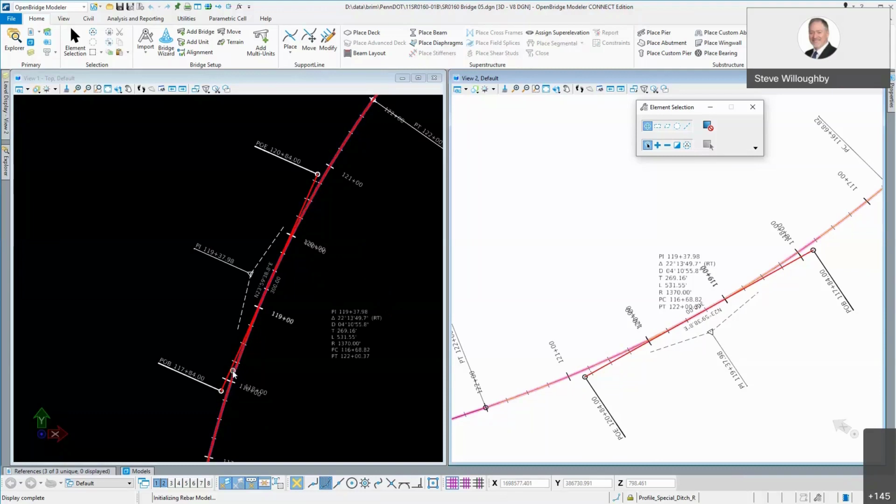And then I first constructed this line right here. So in that same geometry file, I constructed that tangent, that local tangent, at the station we were given in the plans. And then relative to that line, I offset some other lines to represent the edge of deck, and then eventually the gutter line as well.